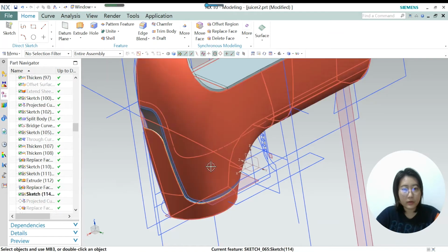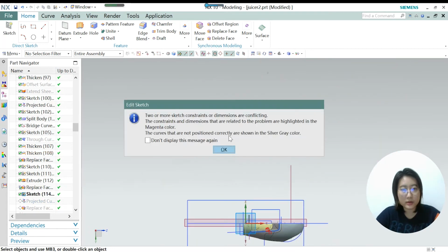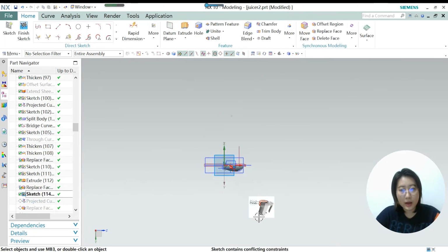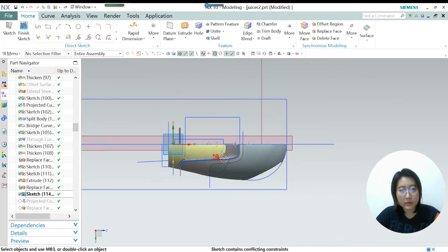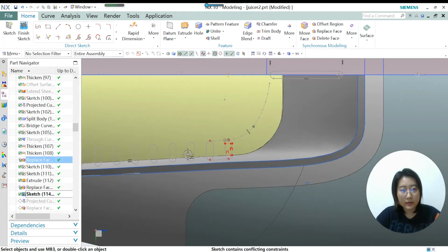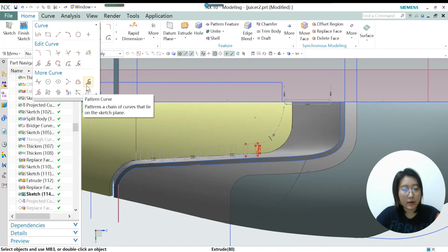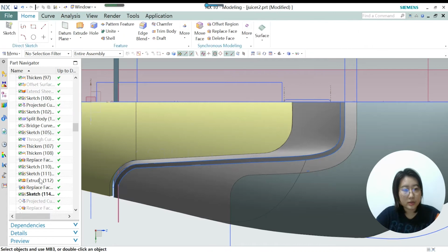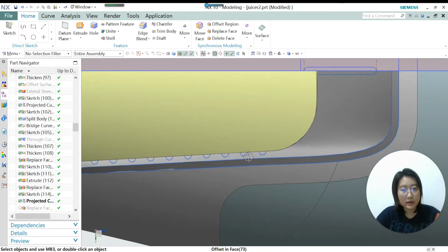So in this sketch, in this plane, I created a 2D sketch. If you go inside of the sketch, you can see I made these small details here by creating some sketches. I create the sketches along the parts and curves with this line. Let's finish the sketch. And next I do a projection. I projected the sketches on this surface.